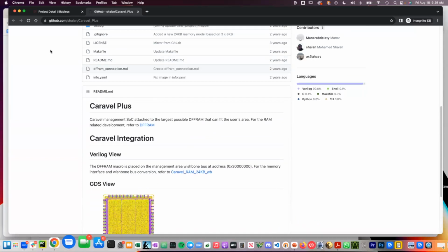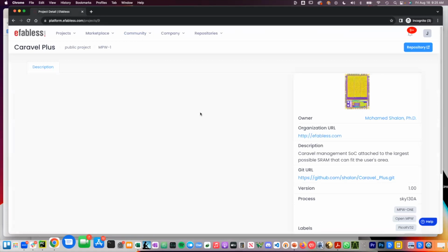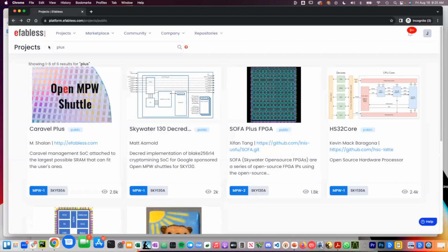And in terms of DRAM, no, it's not possible. There's no current embedded DRAM. If you meant DPRAM, as in dual port, yes, there is a dual port cell, and there are dual port memories in the IP set that's already public. So there's a DP macro, one of the IPs from Open RAM that has already been brought out, and it's in the community. I think that was developed by Matt Goodhouse at UC Santa Cruz.